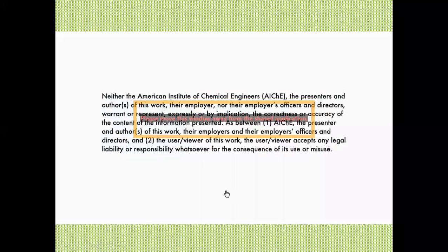Valve trays, along with sieve trays, have dominated for the last 40 years. Valve trays generally are proprietary and contain movable valve units. When the vapor rate is low, the valve partially closes and minimizes weeping by restricting the liquid flow through the tray holes. At high vapor rates, the valves deflect the vapor flow. This reduces entrainment by creating a weaker vapor jet and results in a greater operation range. The valves do contribute to vapor pressure drop, as the vapor must push the valve open.